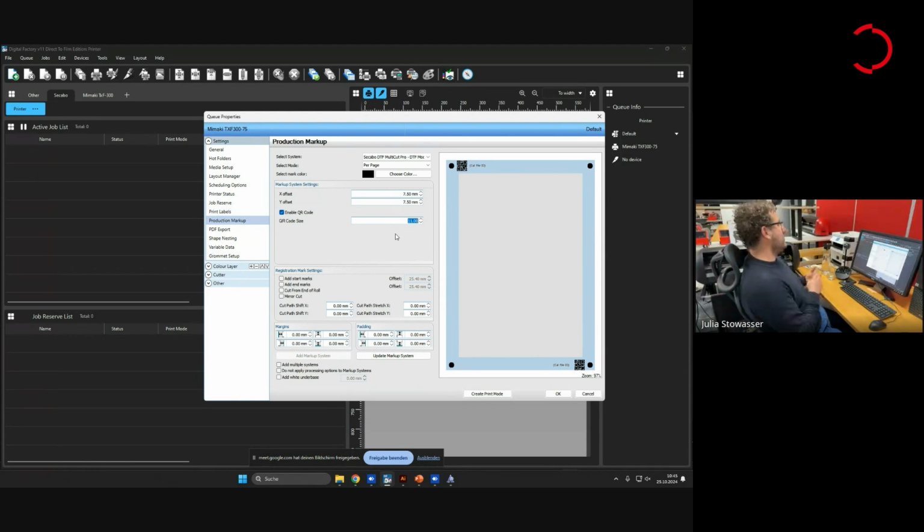It can be really easy to read the QR code, or it can be pretty difficult. Of course, the surrounding light settings are also an important point, but more important is the print quality, the amount of white you put there, and the type of powder you use. We recommend to use 15 millimeter, which makes it much easier to read the QR code.